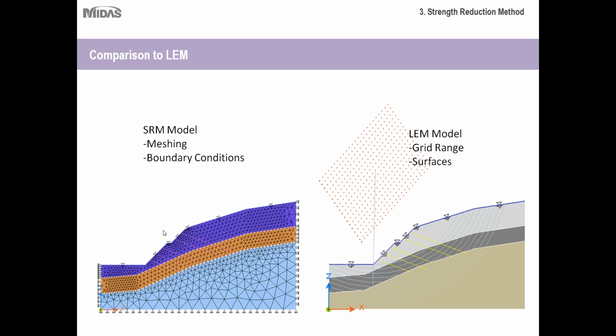So that was what was meant in my previous slide about higher order elements. Higher order elements is just another way of saying smaller elements to calculate more, to get more detailed analysis results. So also take note that you need to create boundary conditions as well for your model just to simulate the forces, obviously, that are keeping this model in place.